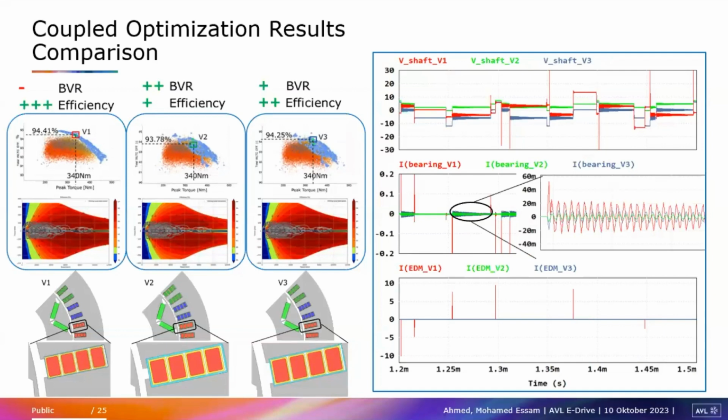You can see how they actually look between the three variants. So as you expected, V1, which has the highest efficiency but lowest reliability or highest bearing voltage, tended to minimize, for example, the hairpin enamel, the hairpin coating insulation, and also the slot paper, which makes sense. You get the most copper fill factor. And you can see here the V2, which reduced the efficiency but maximized the reliability, or minimized the bearing voltage ratio. It maximized both insulation, and V3 was some kind of middle solution.